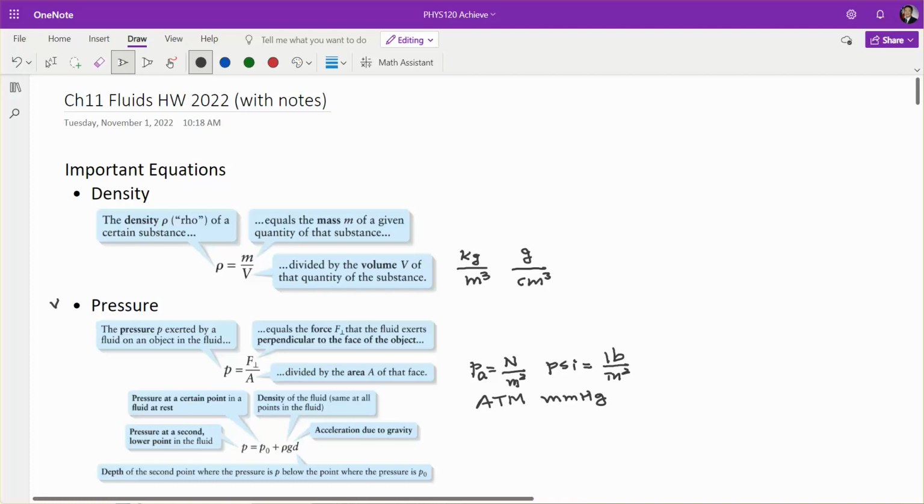The second definition that we give you for the pressure is more general. If you know the pressure P0 at one point, then somewhere else around this P0 position, you want to find the pressure at that position. Normally this position will be lower than the P0 position. Then the pressure P that you try to find is going to be equal to P0, the starting position, plus rho g h.